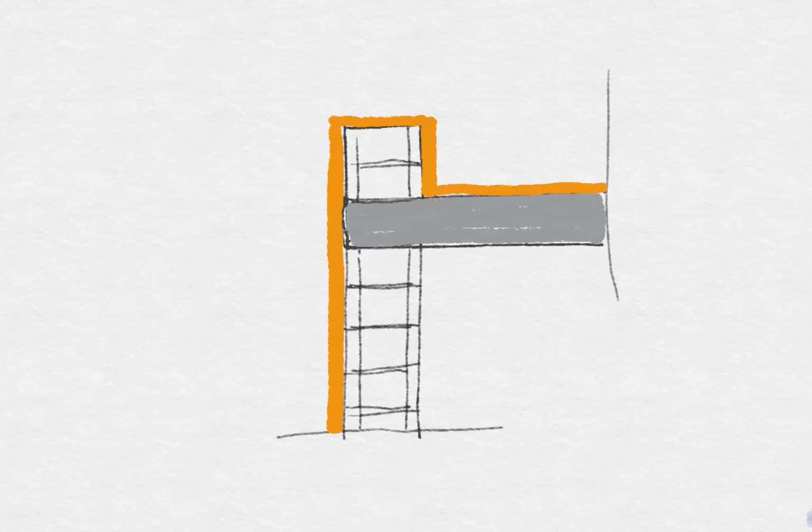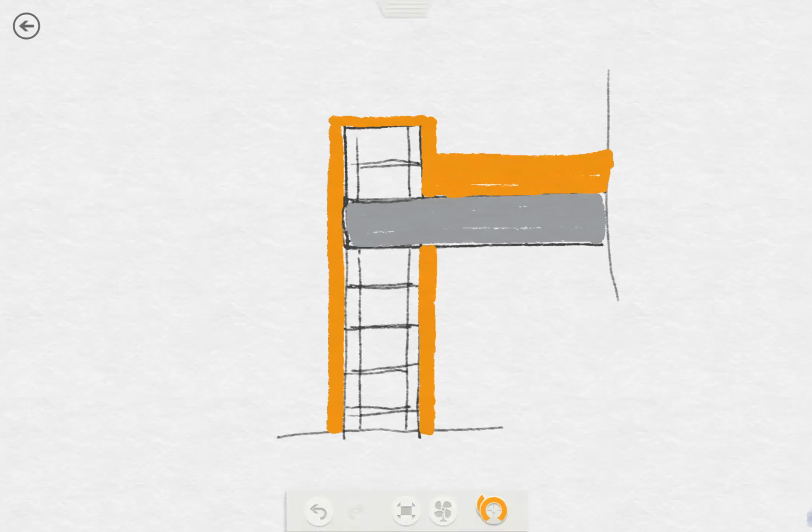For sure, we have to increase the thermal insulation in the roof, because looking at the loads report, we need the thickest thermal insulation here, and then we need thermal insulation inside the wall. I will do that. Let's do this, and then we will talk about thickness.